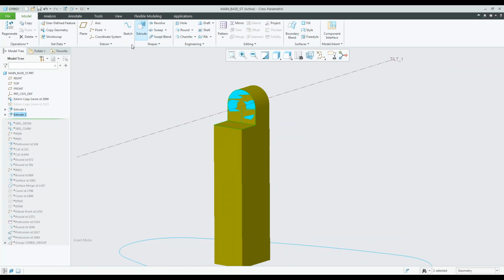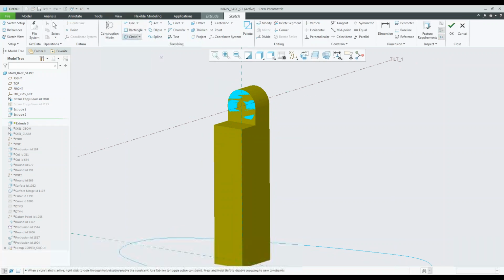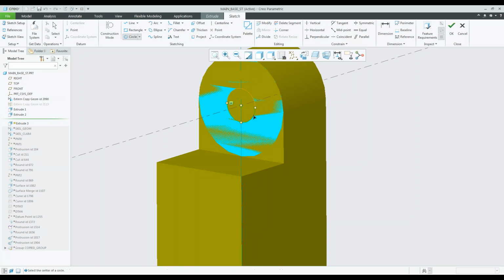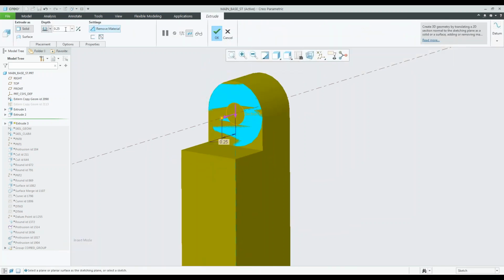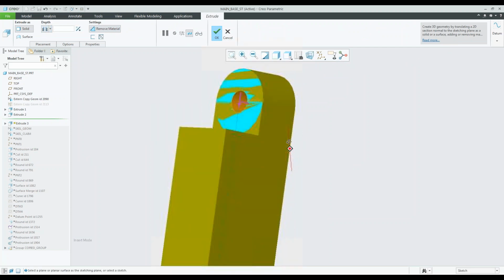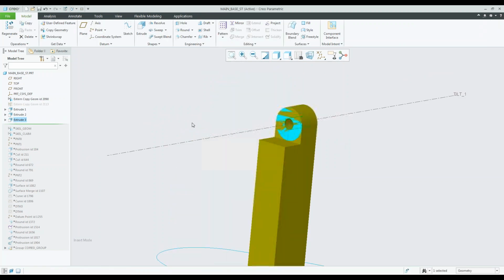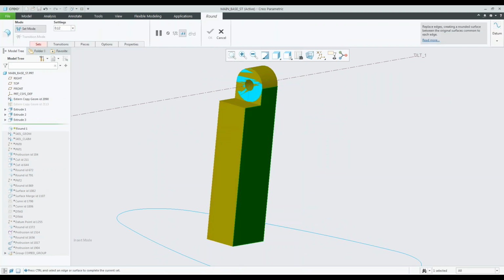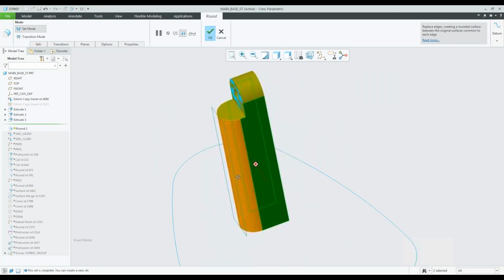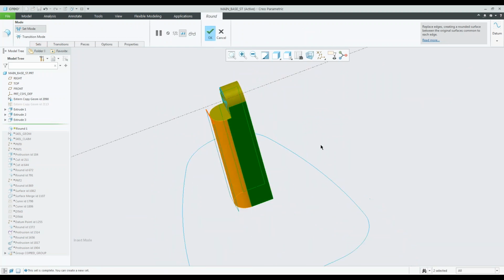And I also want to make sure I have a hole so that we have these components being held together. So let's create the center hole there. Remove material and flip it to the other side, going through all like so. And then since I am the engineer creating the base, you can continue forward with creating all of your finishing designs. So for example, if I wanted to include a round at this post, I can go ahead and create that full round at the post just like so.